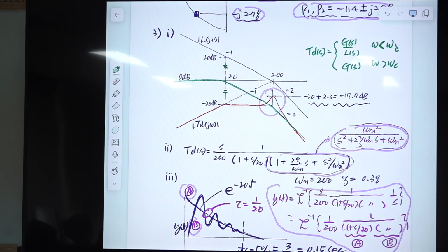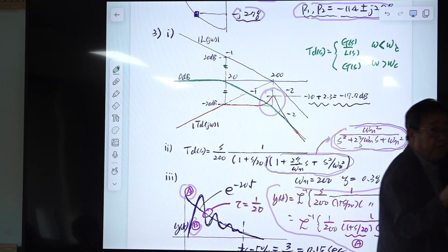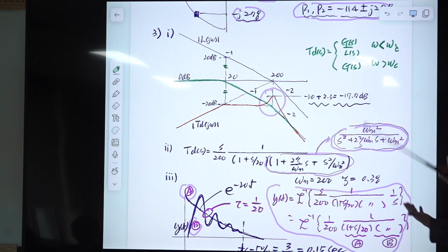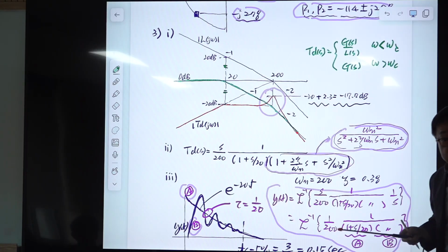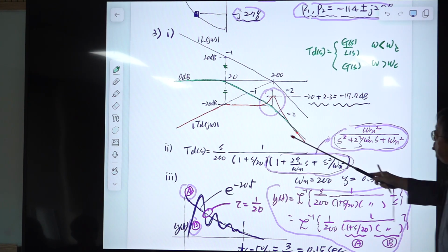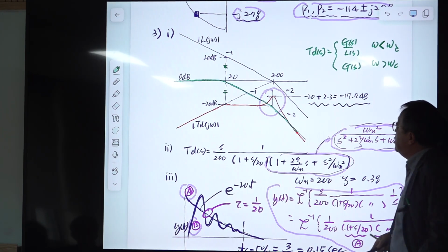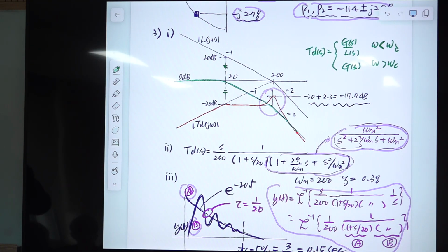You know this, right? Oh, no, this is LS, right? No, GS, right, yes. You already know this, right? Okay. So the input-output transfer function becomes 1 here. But in general, the disturbance to output transfer function is not 1. It never becomes 1. It is this one. So GS divided by LS in linear scale, and in log scale, division becomes subtraction.